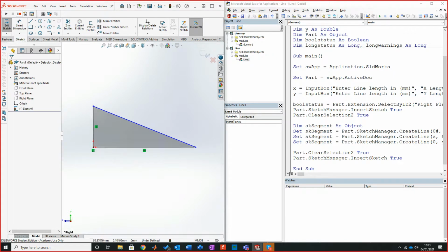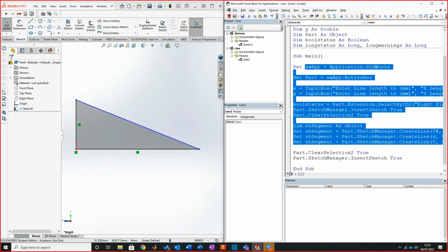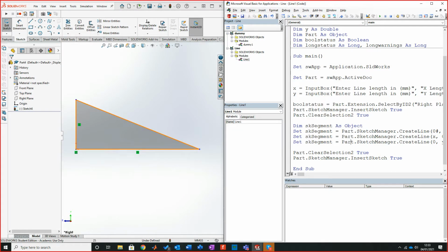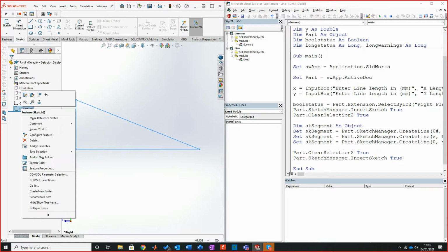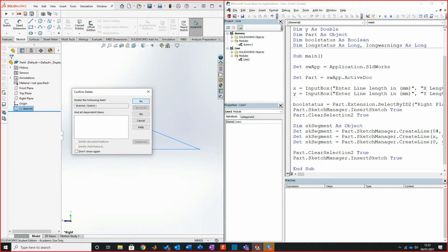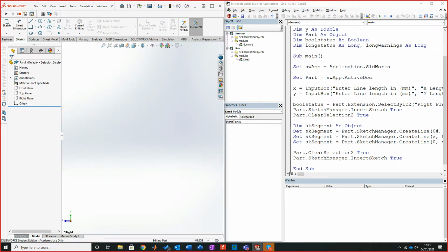purely because defining the sketch is for more of that construction process. If you're leading this by driven dimensions, you don't need to put dimensions onto here, because all your dimensions sit inside of here. The second that you use dimensions on this, it becomes a pain. It becomes trickier than what you'd imagine. So what we're going to do is create a tube creator. If you've not done already, make sure you save anything that you've presently done.